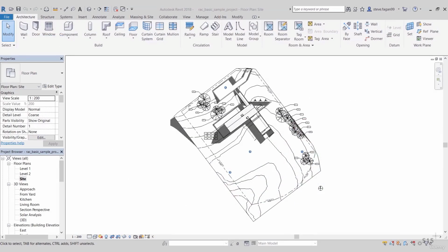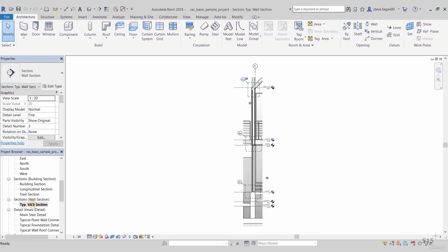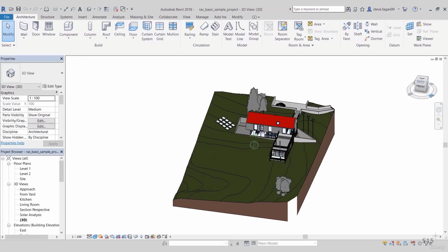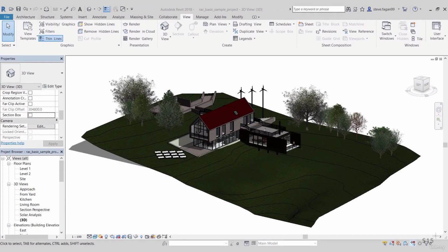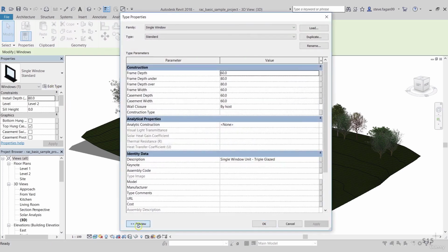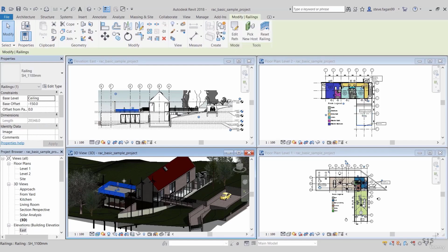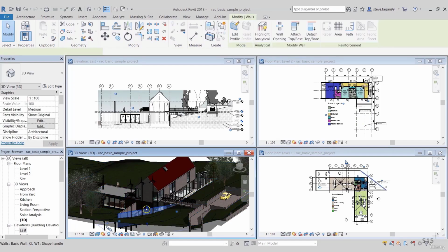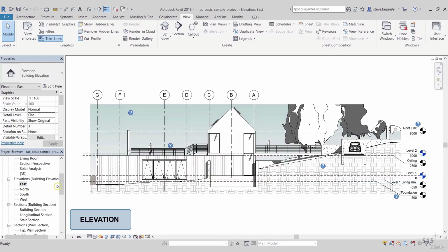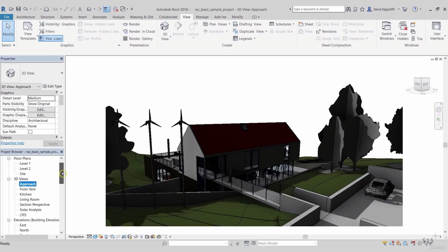In Revit, the project is the single database of information for your design, the Building Information Model, or what is known as BIM. The project file contains all of the information for the building design, from the geometry to the construction data. This information includes components used to design the model, views of the project, and drawings of the design. By using a single project file, Revit makes it easier for you to alter the design and have changes reflected in all associated areas, be it the plan view, elevations, section view, schedules, and so on. Having only one file to track also makes it easier to manage the project.